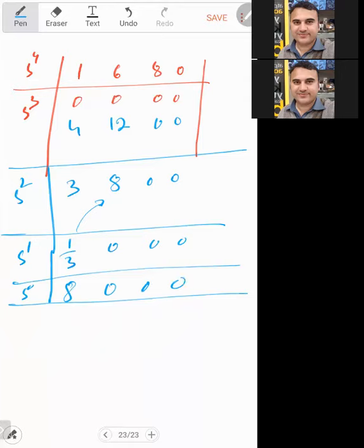Now, the interpretation of this is very much important. Remember that the auxiliary polynomial will introduce the imaginary poles, and they will be symmetric. The symmetry can occur under three conditions. The poles are symmetrical and they are on the real axis. You see, they can be on the real axis.